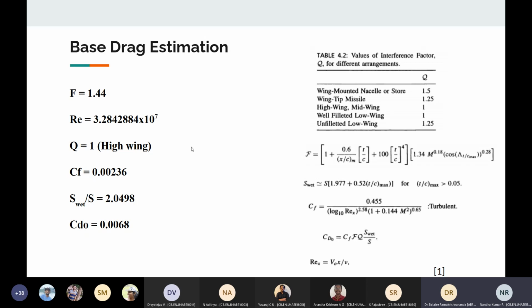So, low speed and high angle of attack. So what will happen? Will the engine hit the ground sometime? Yes, sir. That's what I was trying to say, sir. Why the engine only? The tail will hit first. Tail will hit first, then the engine also. Then how do you take care of it in VTOL? In VTOL, do you bother about the angle of attack? Sir, no, sir. Now you have a contradiction.